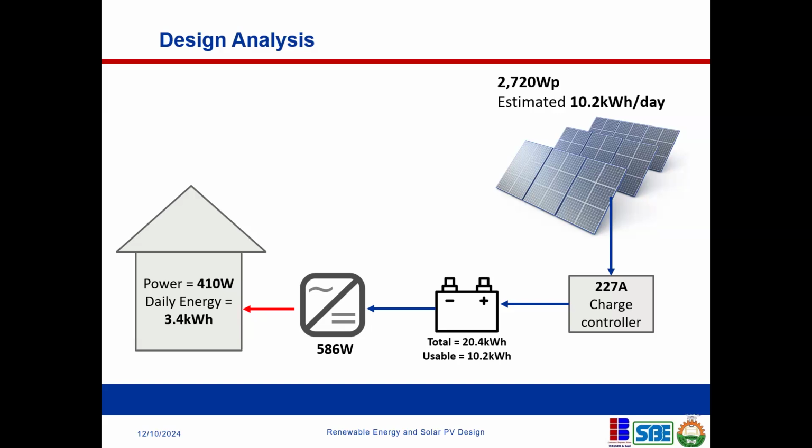We can reduce the autonomy, because we designed this based on 2 days of autonomy. Yes, we can reduce the autonomy to 1 day. That's a great way to do that. Exactly. What if we increase the amount of time it takes to charge, so that we don't need this much capacity of panel array, the PV array?